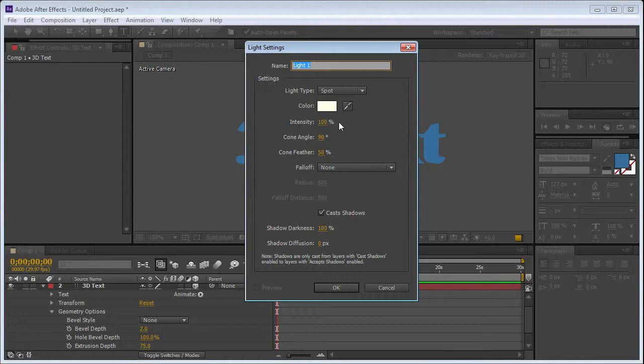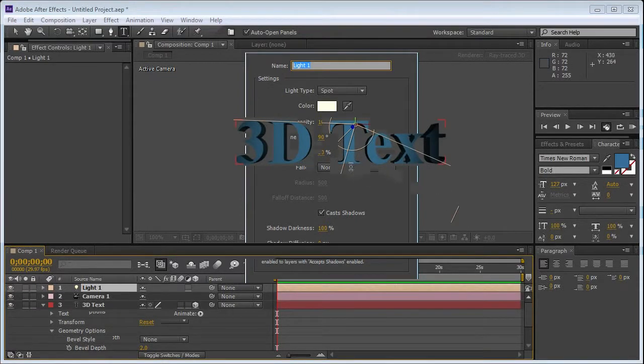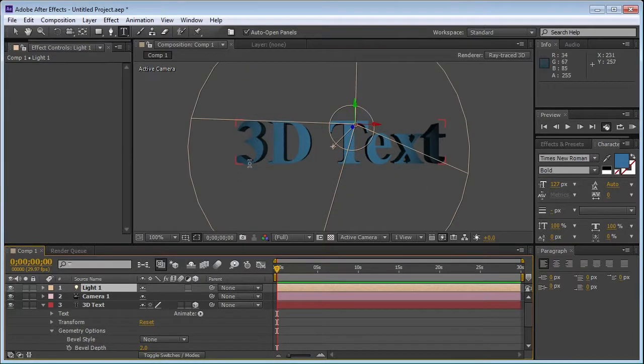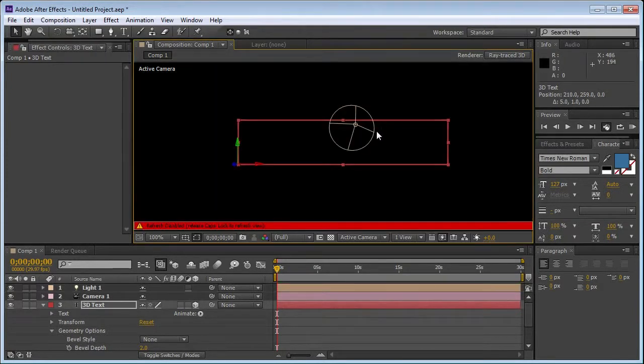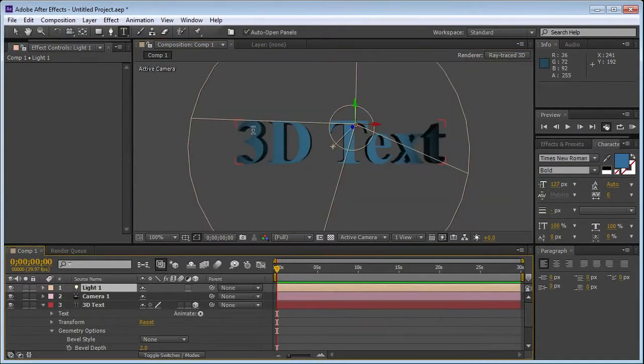And when you get the light into the scene, you're going to notice that, again, it's going to render off that frame. But you can see already how much this is helping us actually see the difference between the face of our text and what's happening with the depth of the shape of it. Now with this light, you can move it around. I'm going to hit my caps lock so it turns off that render. Grab my move tool here, and then we can, not the text, we want to move the light itself.